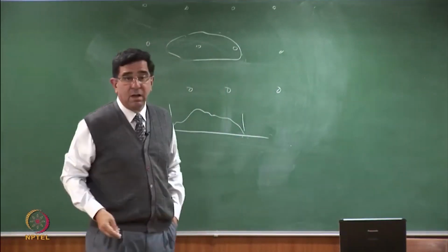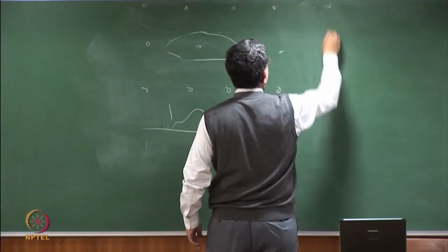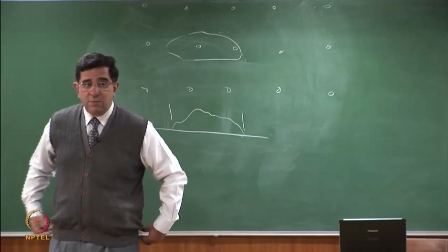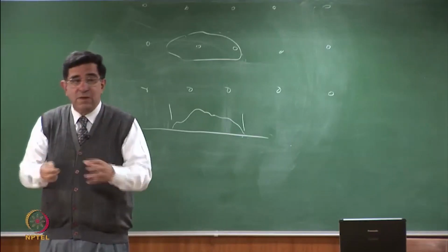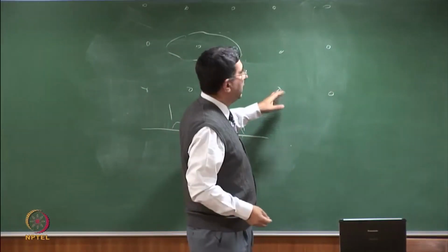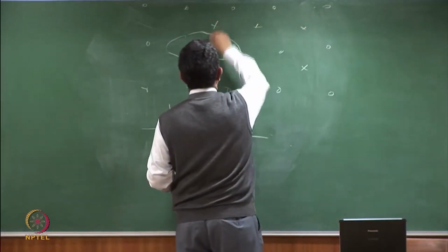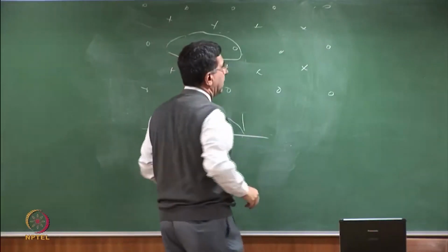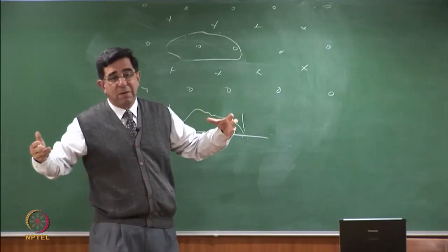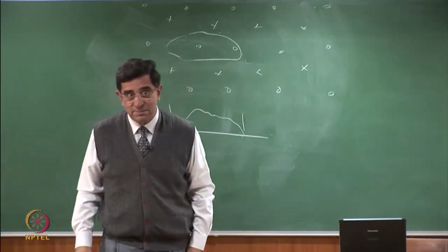And if I detect something which says this has gone beyond, then I'll make a coarser grid. Agreed? And if I want to fine tune it, first I'll do the boundary. I know that it is not reached here. I know I'm getting a reading here, so then I'll do the finer grid. And then on the basis of this finer grid, I should be able to give you how the contaminant varies in plan. Still, I will not be able to give you how it varies in depth.